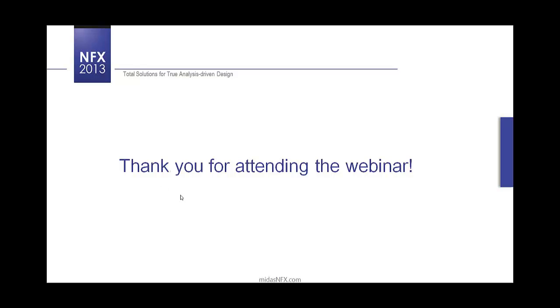Now the question is, can I make different mesh granulation for different areas of the geometry? This is a question from Florin from Romania. Yes, you can do all kinds of meshing using control of the mesh density, and we also have something called adaptive meshing. Related to the results, for linear static analysis, you can use this feature to tell the solver to remesh at certain areas of the model.